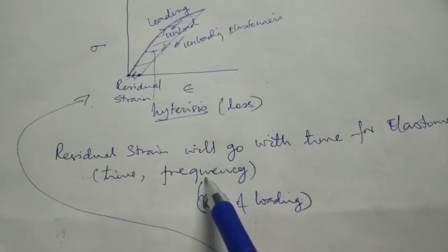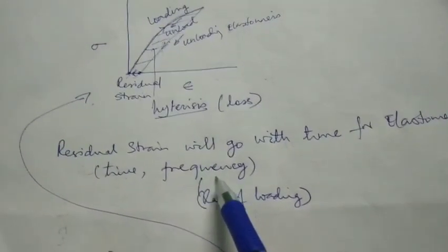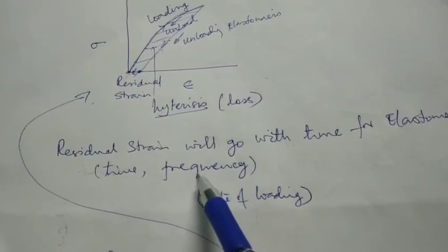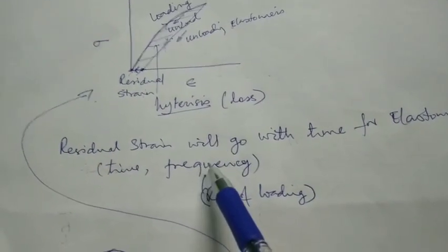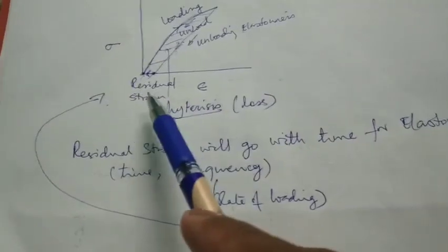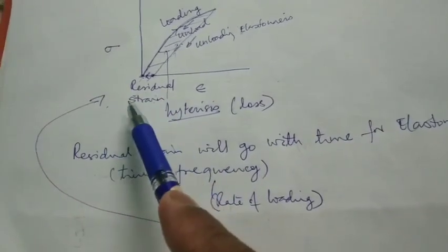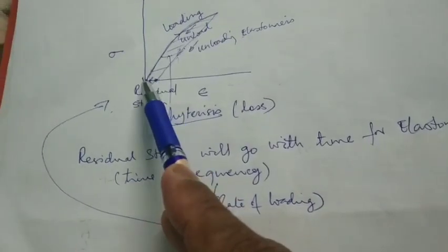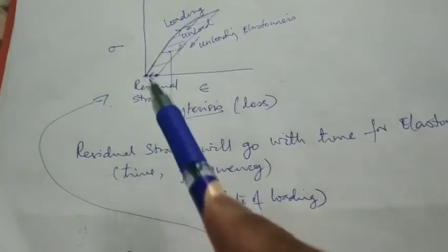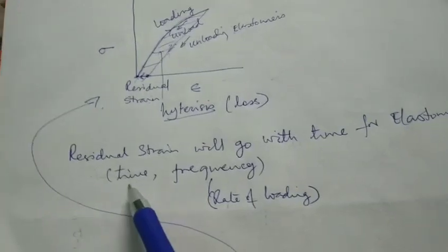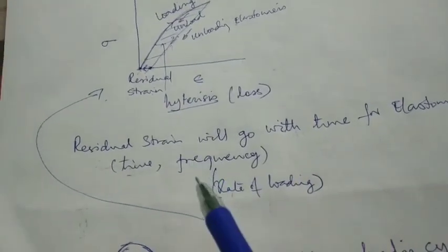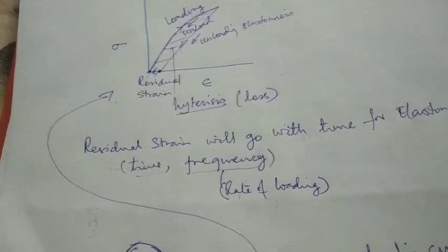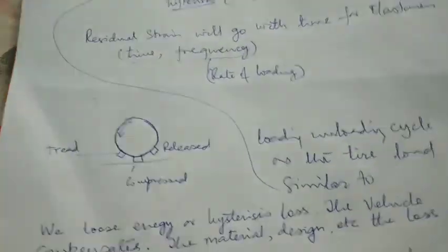If you are continuously loading and unloading it, then the residual strain will have a certain way of recovering. So this residual strain will take time depending upon the material and depending upon the frequency, the rate of loading that is taking place.